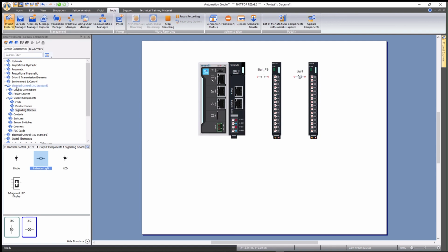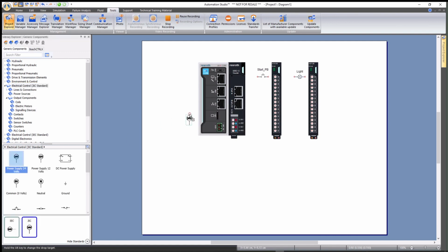Now we have to complete the wiring, so here let's first power on the PLC, so it needs 24 volt to be powered, and then we need, so this is how we power the PLC. Now after this, we have to power the input and output card, so this is the connection you have to do to power the first card. This is the input, this is the output here. Now I powered these two cards.